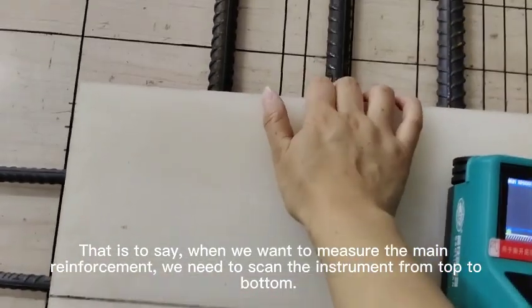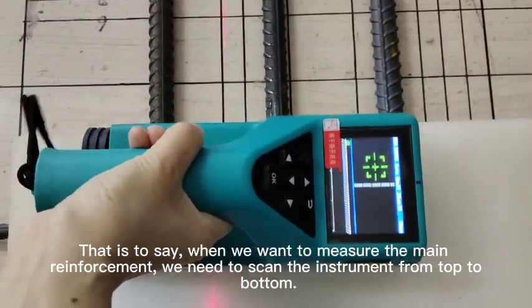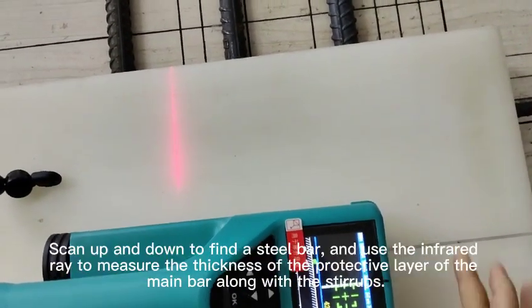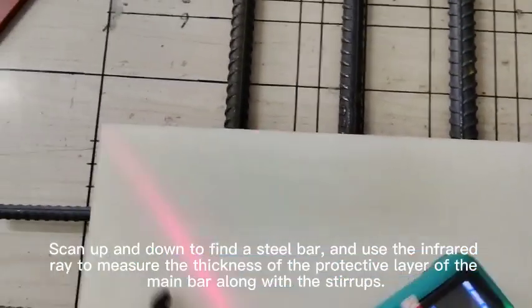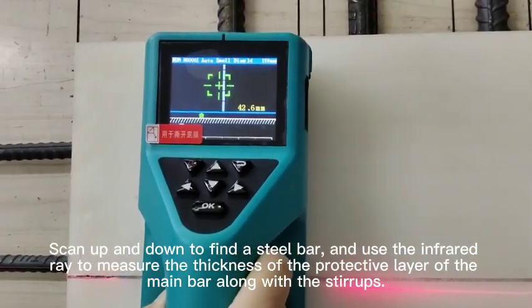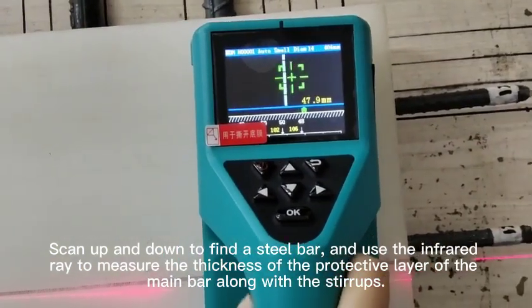That is to say, when we want to measure the main reinforcement, we need to scan the instrument from top to bottom. Scan up and down to find a steel bar, and use the infrared ray to measure the thickness of the protective layer of the main bar along with the stirrups.